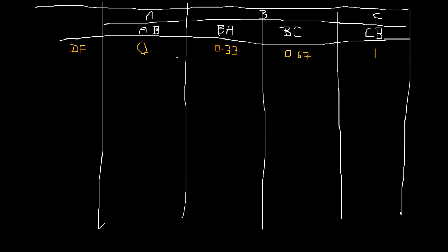Here it's 1, right? Here it's a fixed support, so sigma M is not equal to 0. Here at B it's a continuous support, so sigma M should be 0 because there are two or more members.